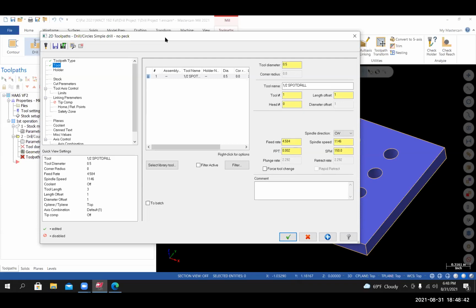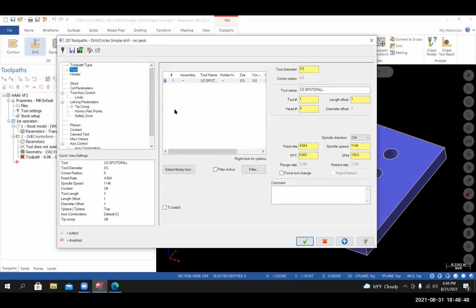I think we had up to 450 tools in that library. If you did not have that set, when you double clicked on the tool, it'd be added to our tool list with whatever number it was assigned to coming out of the library. So tool number 1, first tool in our tool list. Under tool settings, I had assign tool numbers sequentially checked.